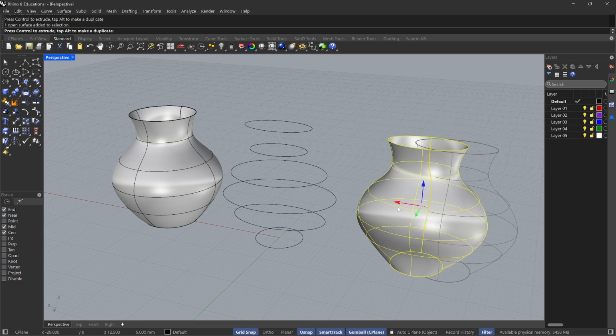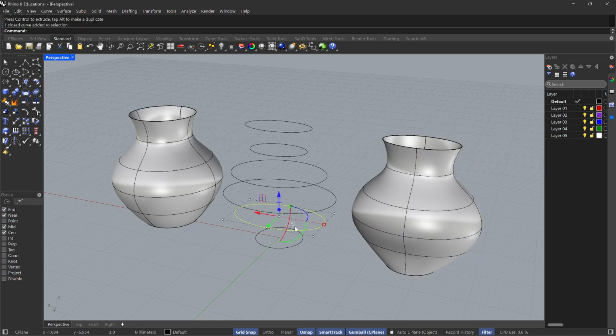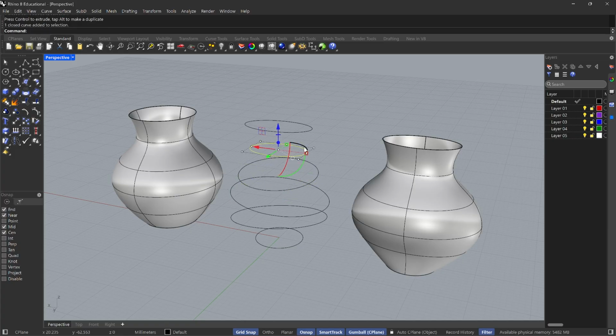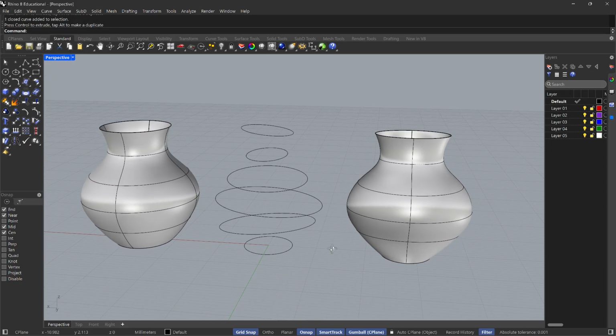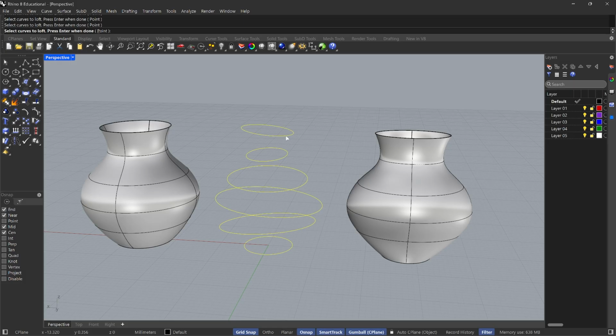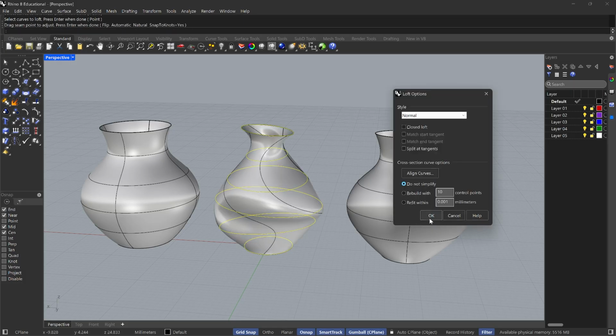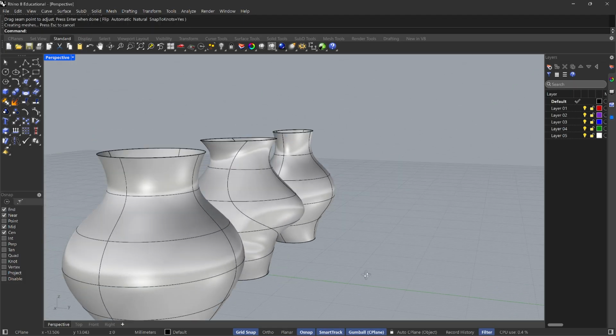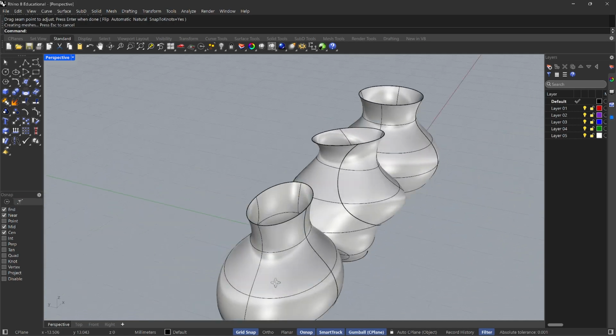In Rhino, they call the drawn lines curves, and the objects are referred to as surfaces or polysurfaces. In this case, I'm taking the exact same curves and I'm using the rotate tool and just changing the orientation of those curves a little bit in space, just to knock it off of centeredness. And I will use the Loft tool again on this. Again, doing these in the correct order, then pressing Enter. And you'll see that now I get a really different result. It has this kind of inherent twist in the form.